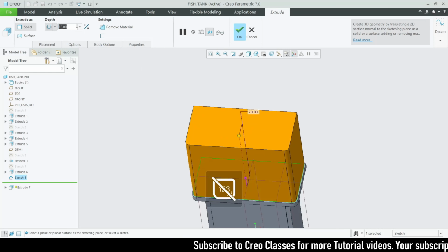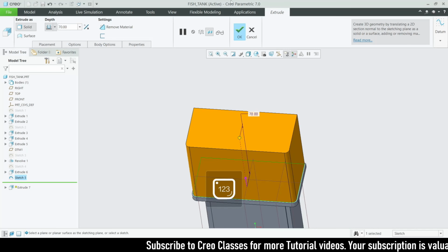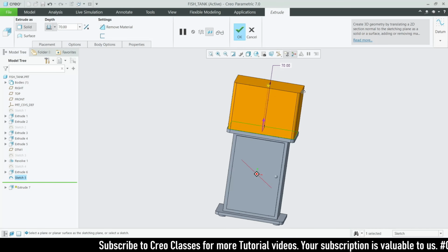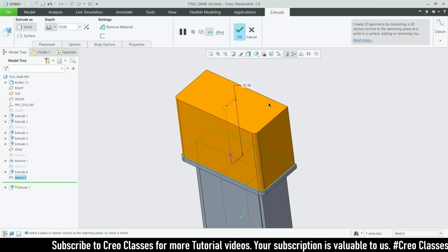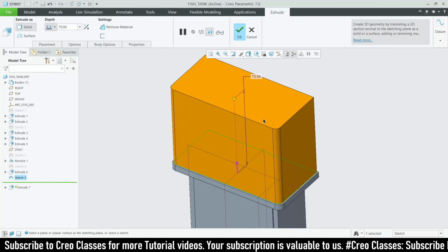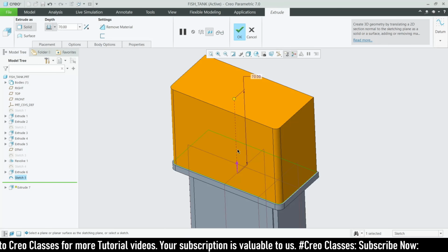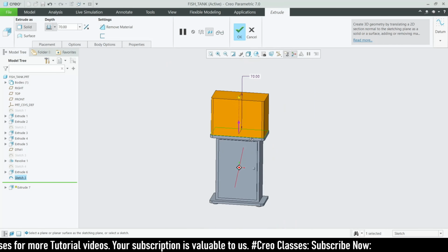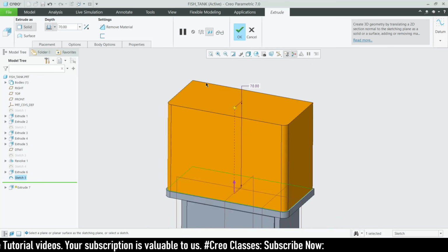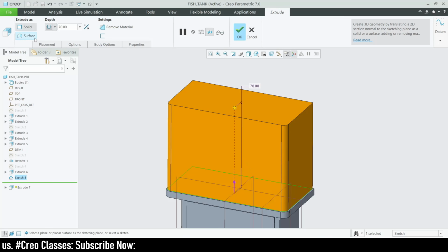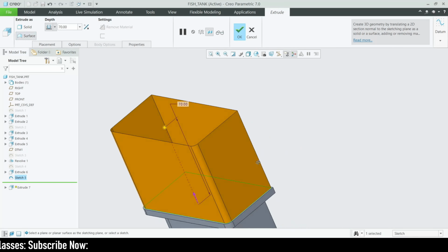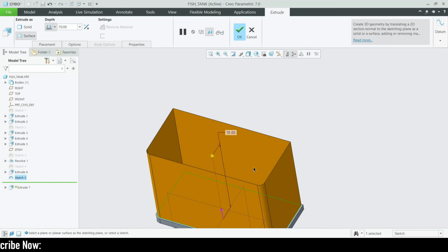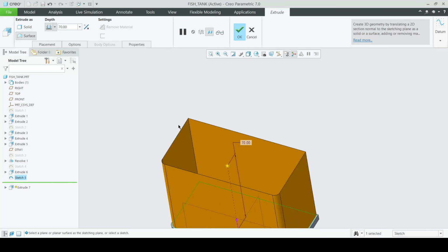This extrude length will be a value of, sorry, 70. Okay, so this will be like a shell part, right? Because inside this we are going to flow our water here, for the fishes, right? So for this, you can complete this sketch and go for the shell option and create a hollow feature here, or you can directly go for the solid, or go for the surface like this, but this surface doesn't suit well because it has a very low thickness.